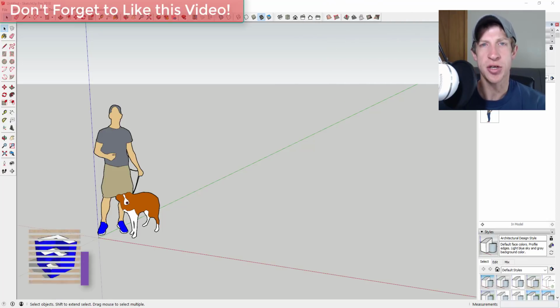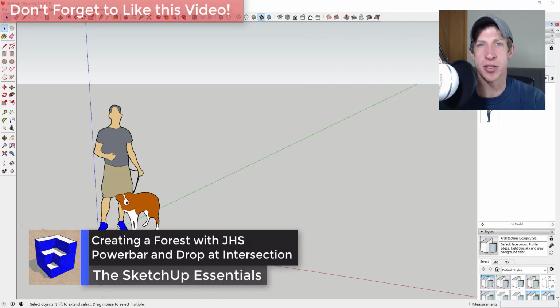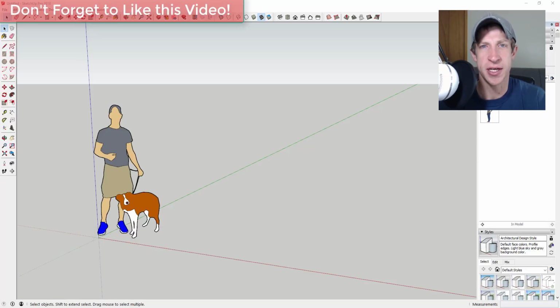So in this video, I'm going to show you how to use JHS Powerbar's drop components function, along with the random scale and rotate function, in order to create kind of a random forest within SketchUp.